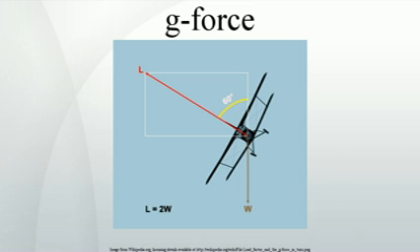If the accelerometer is rotated by 90 degrees so that it is vertical, it will read +1 G upwards even though stationary. In that situation, the accelerometer is subject to two forces, the gravitational force and the ground reaction force of the surface it is resting on. Only the latter force can be measured by the accelerometer, due to mechanical interaction between the accelerometer and the ground. The reading is the acceleration the instrument would have if it were exclusively subject to that force.